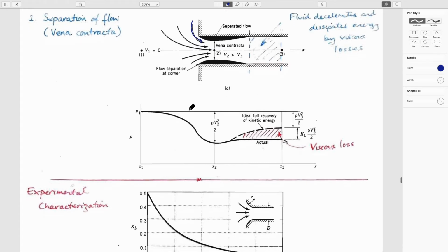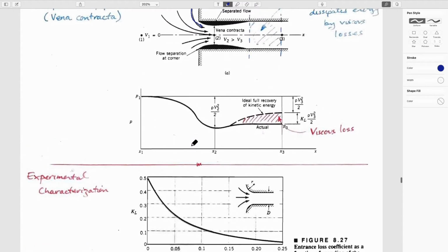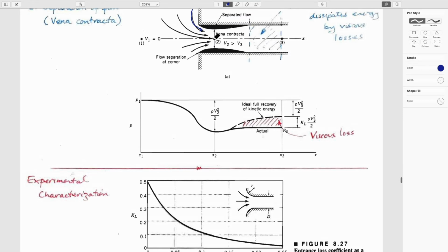And so you can get those effects in entry into a pipe, and that can give an effective diameter of the pipe which is reduced, and so the magnitude of the loss coefficient is larger here because it's squeezing through a smaller area, and therefore it's going faster here than ultimately it's going in the rest of the pipe.